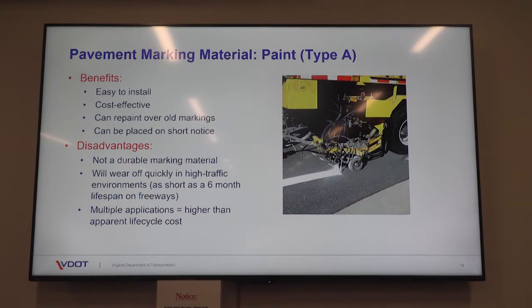Actually, last week we had VDOT come out and do a retro reading on it. After 6 months, it's still getting anywhere in the high 200s, low 300s, versus the standard type A, where we're getting around 90 to 100. So within the first 6 months, it's standing out pretty well. The real test is to come once we put snowplows on it. So we should know more as we go along. But as of right now, it's doing good. It still has a wet reflective. It's not where we want it, but it's holding up well.